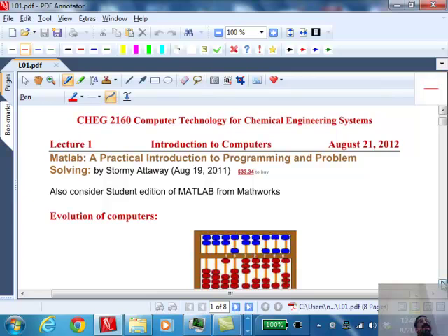So typically these days, because computers have played such a big role, you'll have something called a distributed control system. You don't go into the plant. The plant will have operators on the floor, but as a process engineer, you're going to be sitting in front of a computer and you will see these nice diagrams flashing in front of you with the pumps, and you'll have controls. You can say, increase the pump pressure or the flow rate, just typing the number into a small box, and then it sends a signal, and the pump power is increased, for example. Or you may just want to monitor the temperature or the flow rate of gasoline. So we interact with computers, and the distributed control system is one interface between you and the chemical plant.